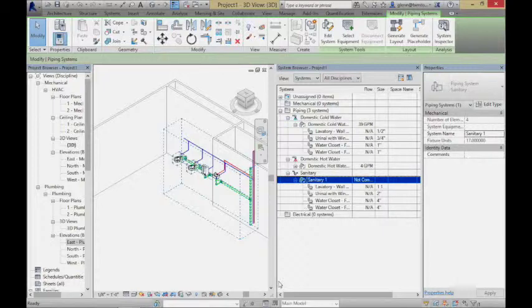There are also loads coming from the fact that we're losing heat to the outside on a cool day like this. If we're trying to keep the space heated, we're losing heat, so we may need to supply heat back to the system to keep us at what's considered a comfortable level. As we design these things, there are ranges of comfort levels that we try to keep things at to keep the buildings serviceable. And we can have a very big impact on the design of all these systems just by choosing what the set point of the system is.